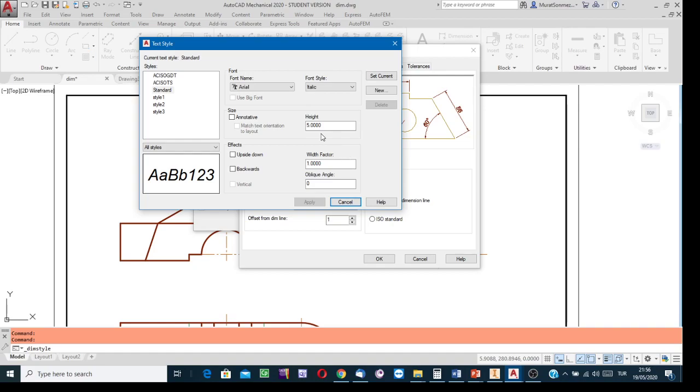So into this box, instead of writing the font height, write the result of that calculation. Remember, I repeatedly give the same notice: the recommended font height times the inverse of the scale factor. Calculate it, and then write the result of that calculation into this box.